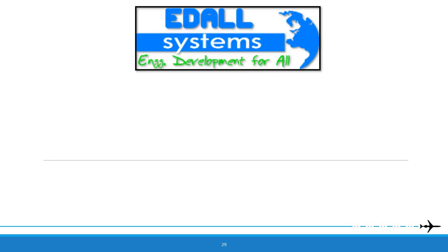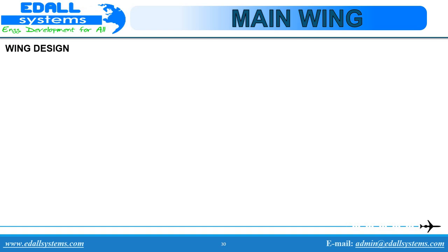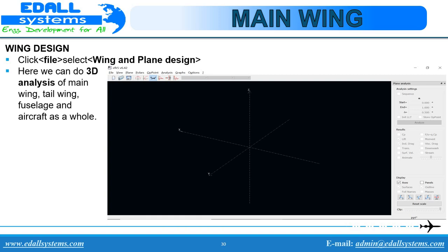In our previous session, we had discussed the airfoil graph analysis. Now let us start off with the wing design. First click on File and select Wing and Plane Design. Here we can do 3D analysis of the main wing, tail wing, fuselage and aircraft as a whole.